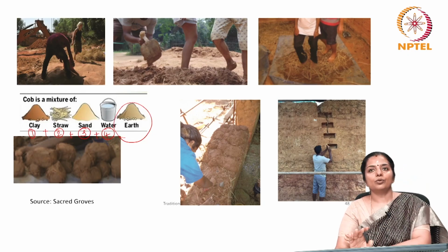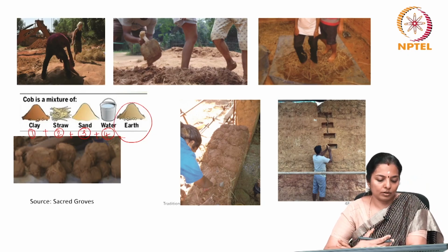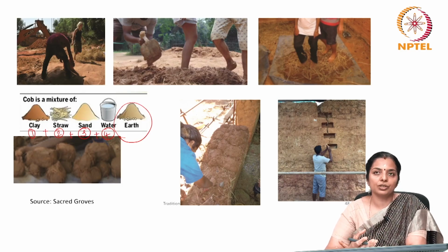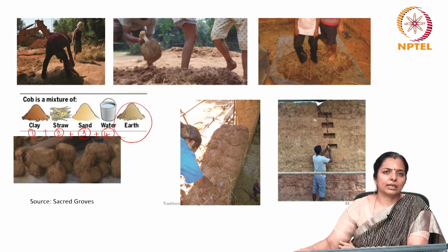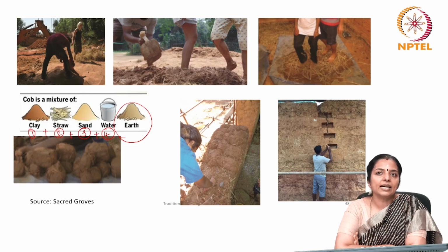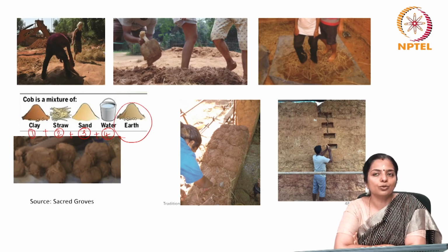And what you do now is you place the tarpaulin on a firm surface, you place all this mixture and you dry mix the subsoil. You add sand, which is optional actually, but it's best to have sand, and subsoil in appropriate amounts as many times as necessary to create a uniform mixture. You flip this mix. Sand is only introduced when the soil has more clay than is necessary. So, based on the nature of the soil, you add clay or you add sand.